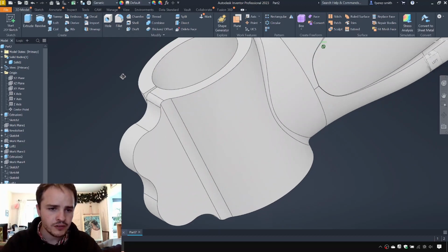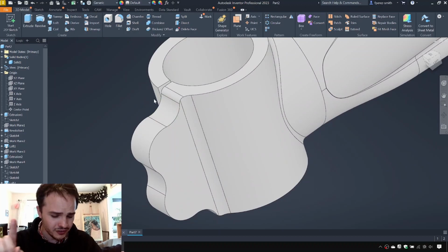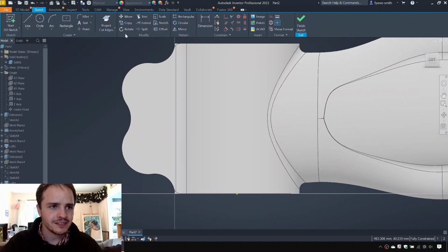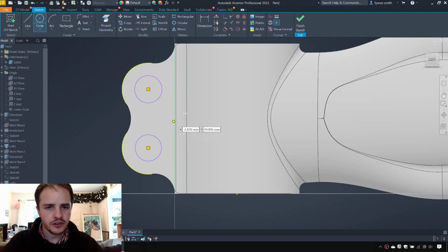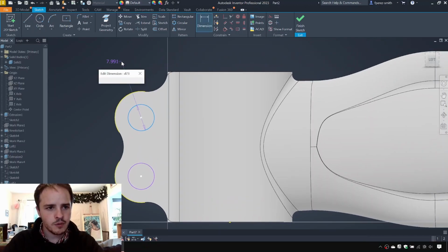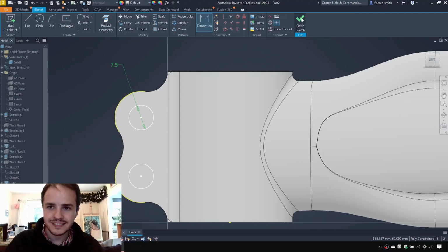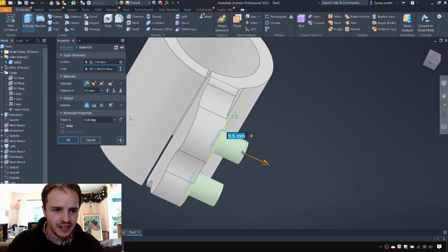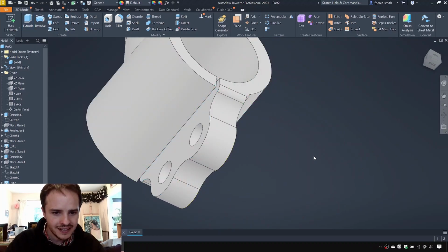So let's go ahead. What we're going to do is just model the internal hole, not the counterbore, for reasons that will become evident later. Okay, so we'll come along here. We'll say create 2D sketch and make a sketch on that. And we'll use project geometry to grab these circles here. And that will give us the center point. We'll make one circle there, another circle here. Use the equals constraint to make them equal to one another. And we'll put in 7.5 millimeters because that's their diameter. Great. And we'll say extrude. Now, we're not including the counterbore just yet. I promise you there's a reason, but we'll share that as it goes.